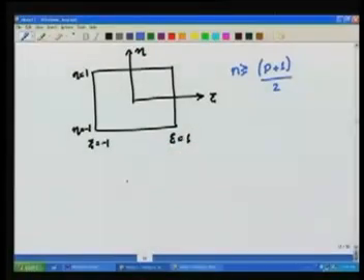So if p is equal to 1 in the psi direction and 1 in the eta direction, then p plus 1 is 2, 2 by 2 is 1, so I can have a 1-point rule. Now for psi, the 1-point rule corresponded to the point psi equal to 0. In the eta direction, this 1-point rule corresponds to the point eta equal to 0,